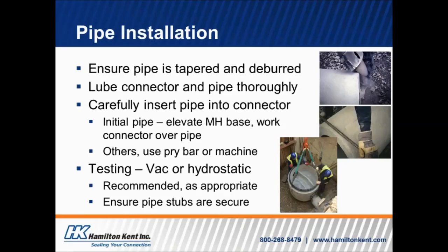So here's just a couple of pieces of information, I think, for pipe installation that I think are important for you to look at and consider. One is to make sure that the pipe is tapered and deburred. You can see over to the right-hand side, the top picture, it's a concrete pipe, and you can see that they're using a saw at the job site to put a taper on that pipe.